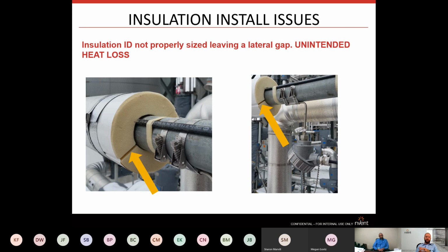When you start getting into really low temperatures and higher maintained temperatures especially, you will have a tremendous amount of heat leaving out of that area, and simply because they didn't oversize the insulation by a 1/2 inch. And it's a shame, because a lot of times the cost is nothing or hardly anything for simply oversizing it. It's really just choosing the right product for a much more robust system.